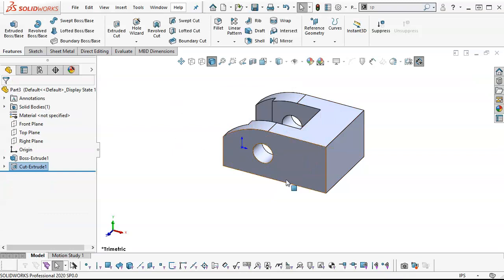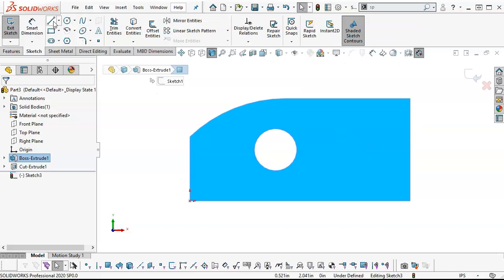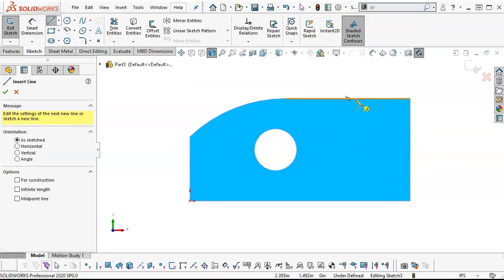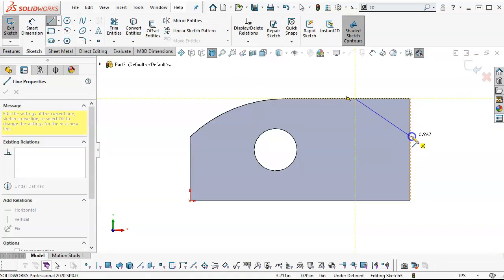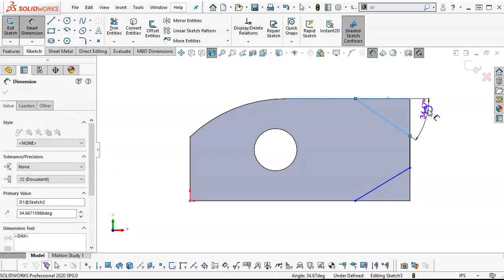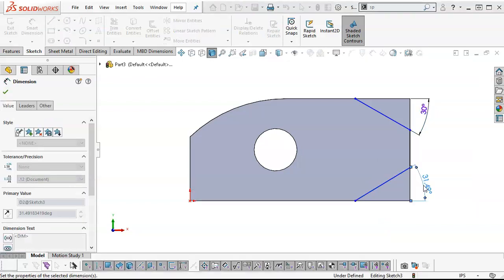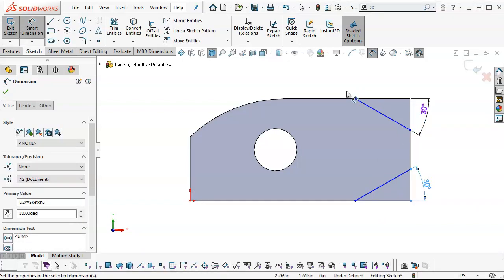set our depth. On the front side, we'll go in and generate our angle. I can leave this probably as an open profile. We have 30 degrees and 30 degrees. So pick the top edge. Whenever I'm doing those open profiles, I do want to make sure that it is a continuous profile, that if I'm setting my pencil down on the piece of paper, it doesn't lift until I get to the end of the profile.